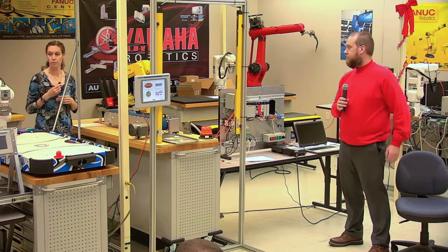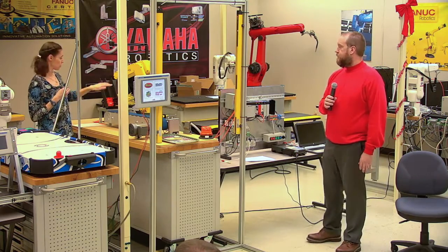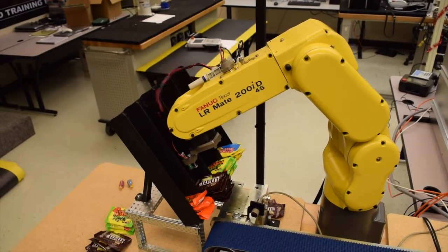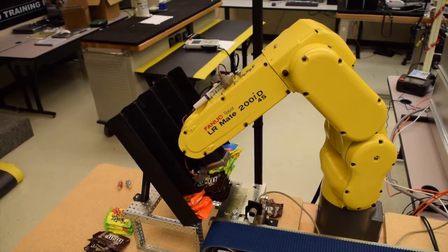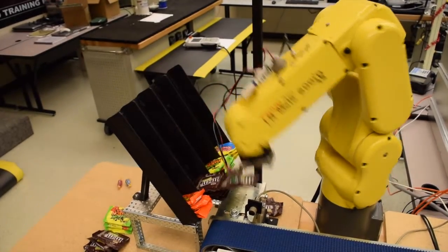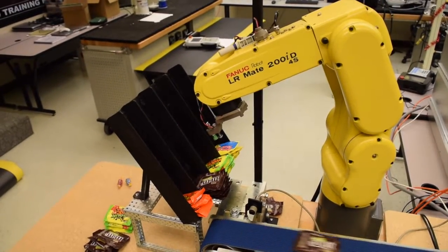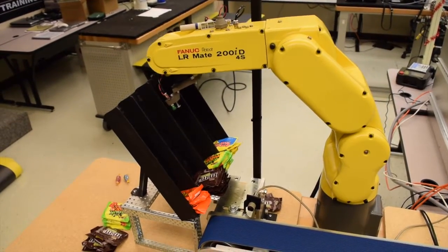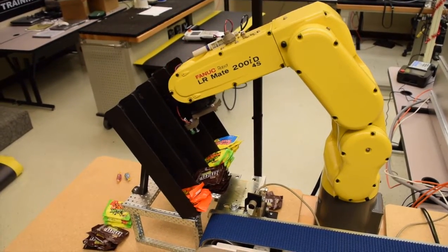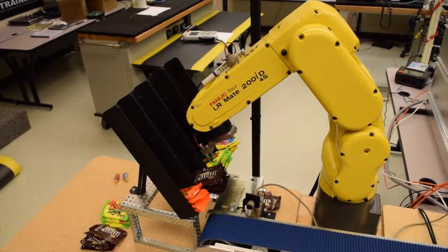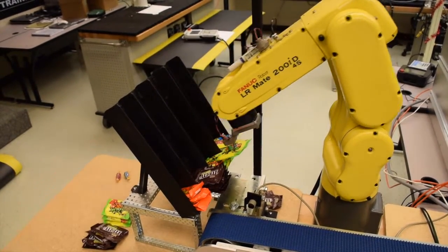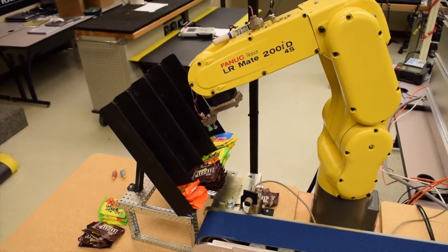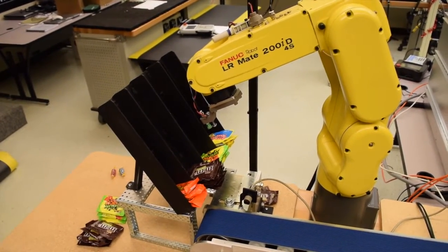When you choose a job, the first time you choose it, the robot goes to a high position and then moves down until this sensor right here is activated. When that opens, because we're using the skip command, it moves to its next line of command, which is to call the suction cup job. That's our pneumatic element. The suction cup then is able to pick that up, and it runs the place job, which starts the conveyor.